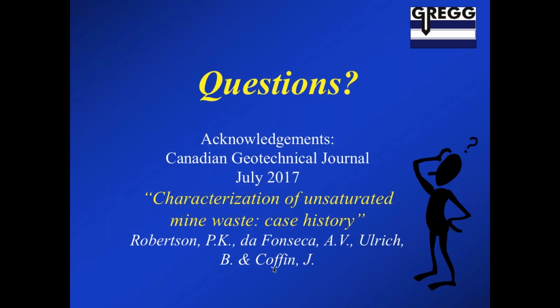But the one that came in says, can you compare shear wave velocity from MASW? I didn't show the slide. I do mention it in the paper that's referenced here in the Canadian Journal, is they only did MASW in a small region down near the toe of the stack. So there wasn't a lot of overlap between the seismic CPT and the MASW, but where there was overlap, the MASW confirmed basically the same values that were measured from the seismic CPT. Obviously the depth was shallower because it was in the toe region. But yes, the MASW worked.